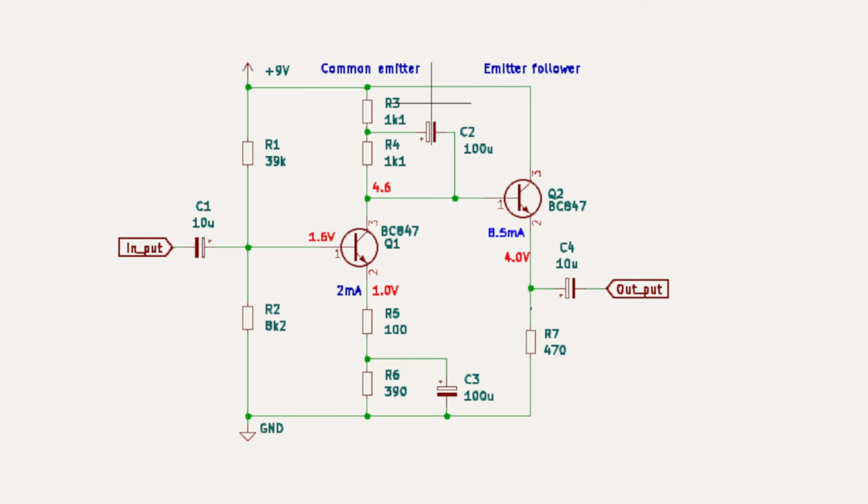I've seen folks describing this circuit as being an example of bootstrapping to increase the input impedance. But how is it trying to achieve this? If we look at the circuit, the DC resistance of the collector is 2K2, the two 1K1s in series. The AC impedance is this 1K resistor, but this 1K1 resistor is totally bypassed by this capacitor.